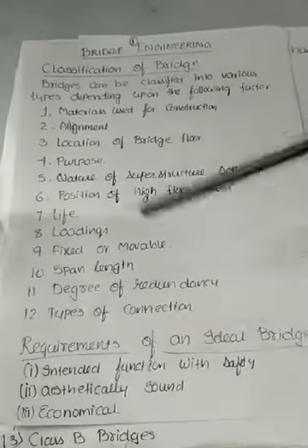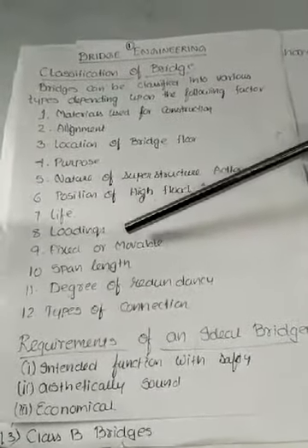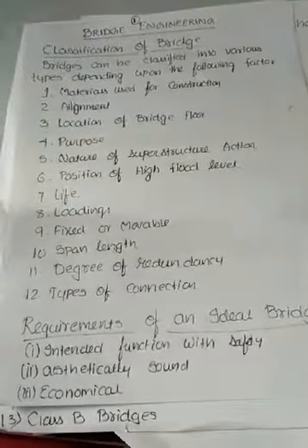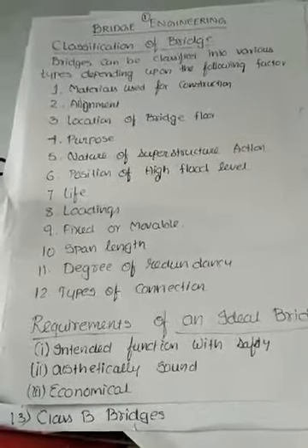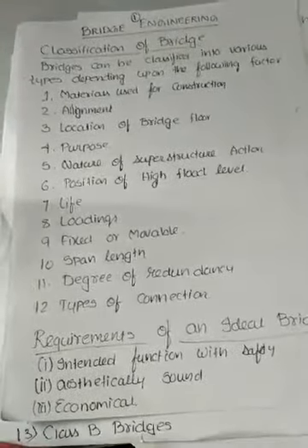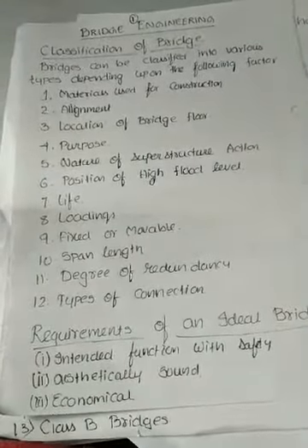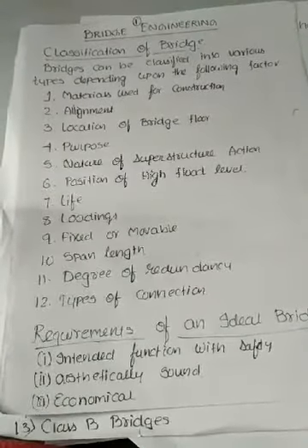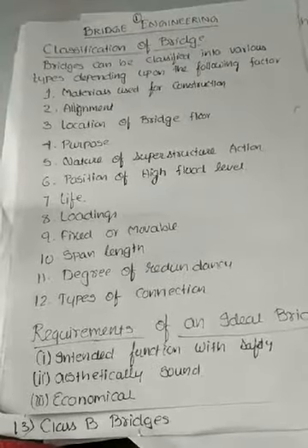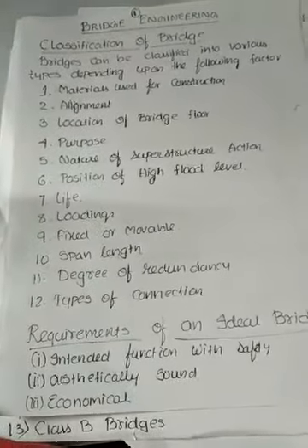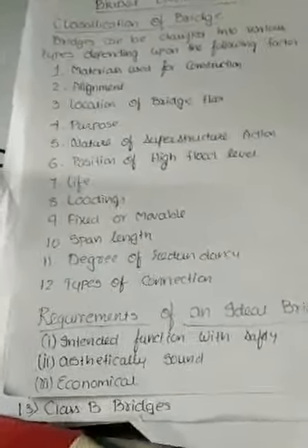Next, flexible or movable. For navigable channels where permanent and sufficient clear waterway cannot be provided, the following movable bridges are used: swing bridges, bascule bridges, and lift bridges.